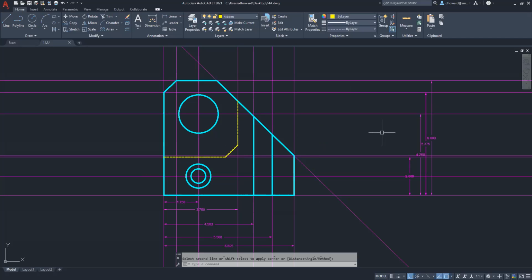So I know I haven't shown you that chamfer before. I'm going to do that one more time because it's new. It's just like the fillet, except when you do fillet, you initially have to give it the radius, right? You type R enter to enter in the value of the radius of the fillet. But with a chamfer, when you click this little drop down and choose chamfer, you type D enter.